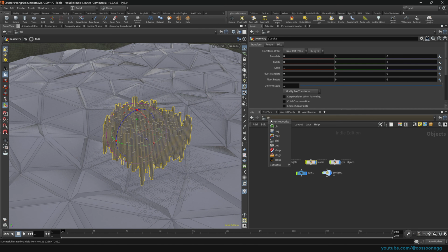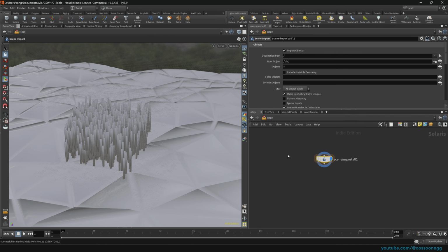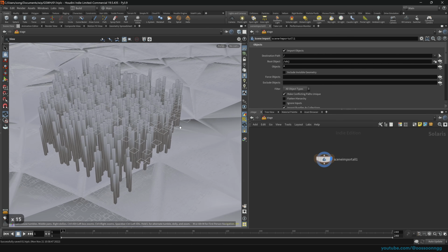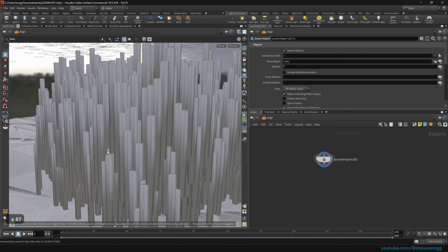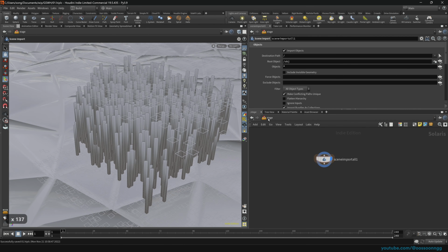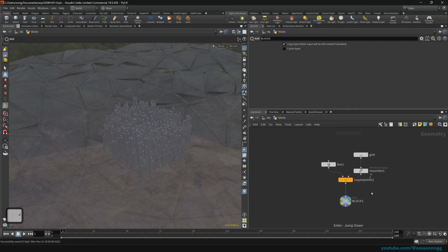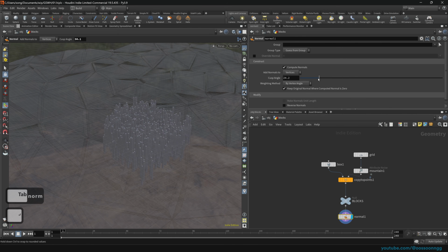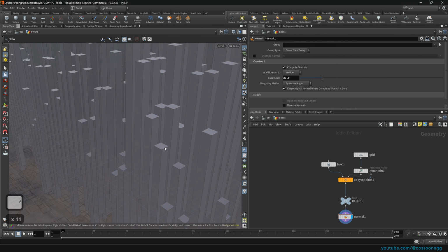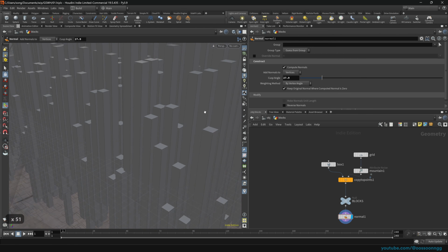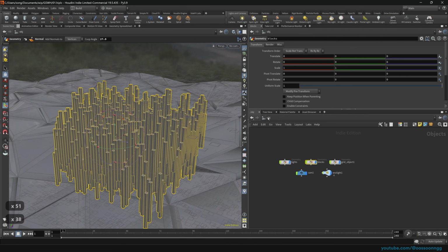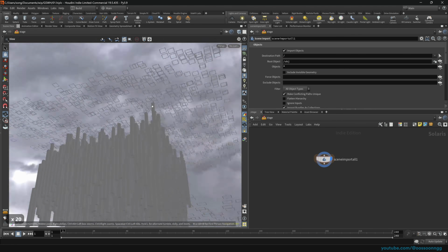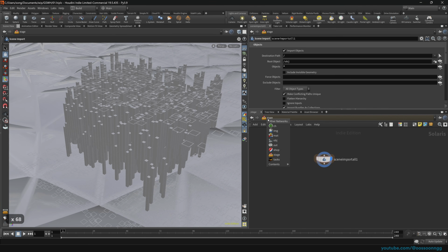All right, so the only problem I see is that when we go to our stage, the normals do not look all that good. So we go to our objects, go to our blocks, and we do the normals. Here we go. Cusp angle, doesn't really matter, 27, whatever. Okay, so now normals should look good. Go back to stage, and indeed the normals on our blocks